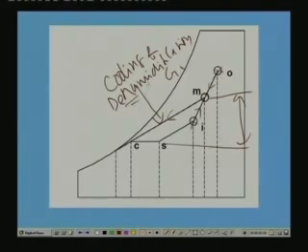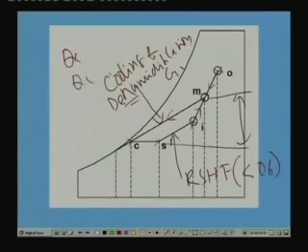So that is achieved in this process, but you find that this point does not lie on the RSHF line. If this is your RSHF line, and this RSHF will be quite low because of the high latent load, let us say less than 0.6. Since this point does not lie on this line, if you leave air at this condition to the conditioned space, it cannot take the required amount of sensible and latent heat loads. So somehow you have to bring this point onto the room sensible heat factor line.